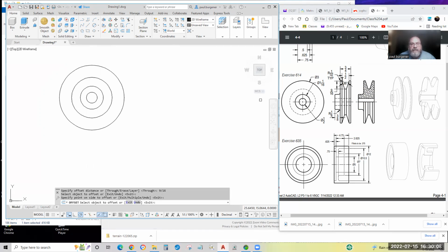The mission is not to develop the right side view. If this is a good choice for the right side view, it looks more like a front view because it shows detail. But anyway, our mission is to develop this crosshatch perimeter, with a notice that the axis of rotation is, I believe, 1/4 inch below the profile. So let's draw some lines for the horizontal lines of our sheet of graph paper, so to speak, and later we'll connect the dots to develop the profile to revolve.